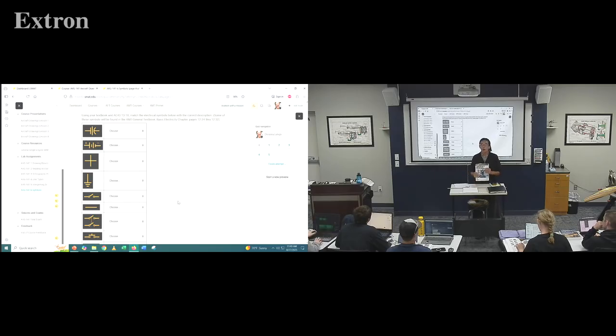So you always go to the aircraft manufacturer's manual, which we have tons of copies of in the library and online. But if something is not in the aircraft maintenance manual, you come to AC 43.13. It has chapters on wood and sheet metal and fuel and everything. Everything you ever wanted to know.